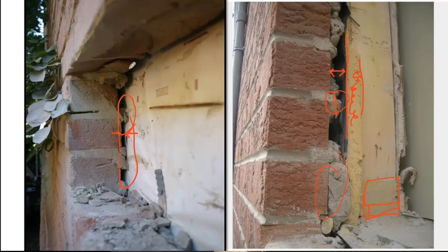The problem is that it runs down until it hits these mortar dams. And then the water has to go sideways until it can find a spot further down. And the moment it changes direction, it builds up water pressure. That's what allows the water to go sideways, right? You need to build up a pressure to create a force to push the water sideways.